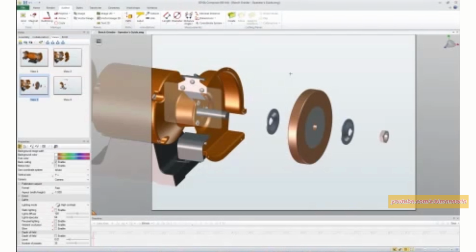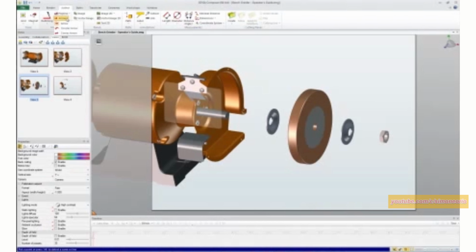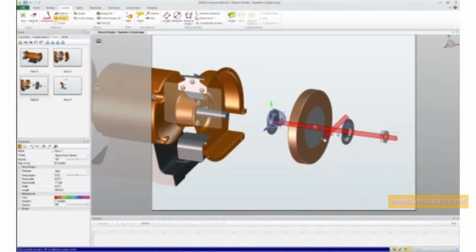When you're setting stuff up in SolidWorks, how nice would it be, really, to be able to add arrows or other fancy illustrative information to your model? In 3D Via Composer, it's actually quite simple. We've got a whole set of tools here that allow us to add different types of arrows. So let's go with this straight arrow. And not only can you create a straight arrow, but you can also lock it onto geometry. And just drag it straight out along that path.